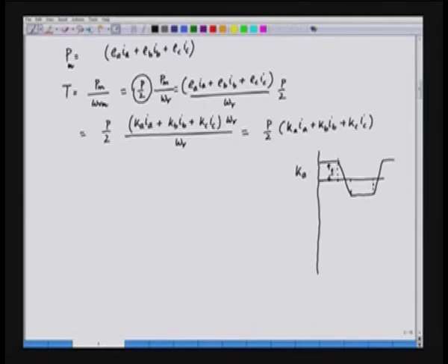So, this is the nature of Ka. This magnitude can be suitably scaled. Say for example, this depends upon the strength of the permanent magnet. This could be, in general, some Kt. So, we can say that the magnitude of this is Kt, the torque constant, Kt is the peak magnitude. Similarly, in this case also this magnitude is minus Kt, and the constant for the phase B, that is Kb, will be shifted from Ka by 120. So, this is Kb. Kb will have a pattern which is shifted from Ka by 120.